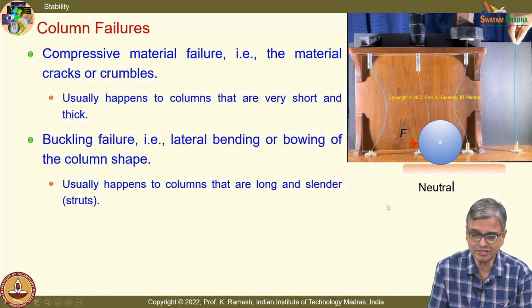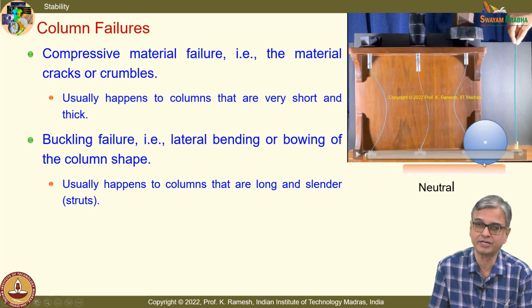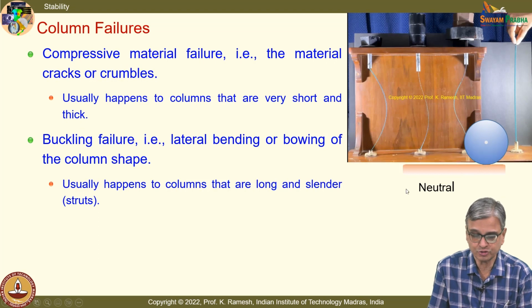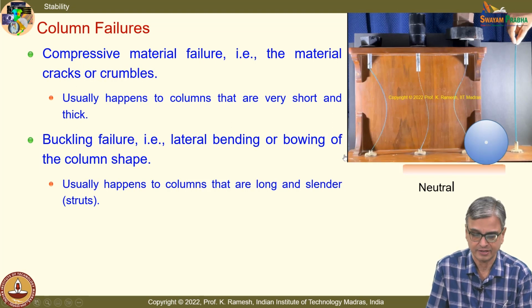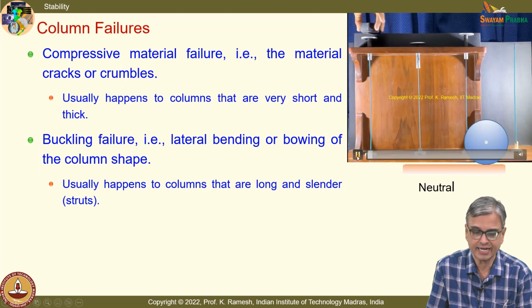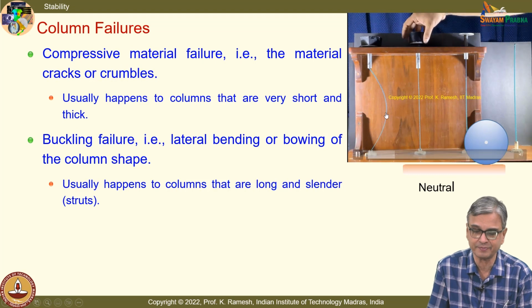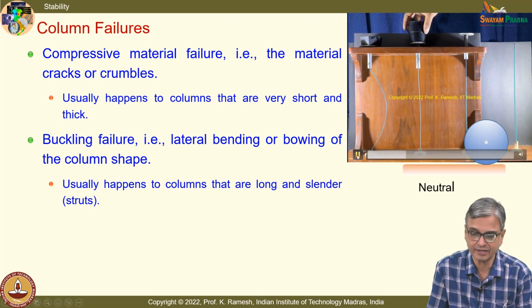See, I have just now said that you have what is known as neutral equilibrium. When I disturb, it goes to another equilibrium condition. I am not sure how many of you looked at this experiment closely. Please watch the experiment closely. You have the idea of this neutral equilibrium beautifully illustrated in this. See, in the first case, I have applied a load which is much beyond the basic critical load, so it has assumed this shape. The second one, you look at it. Can you see that it has started deflecting?